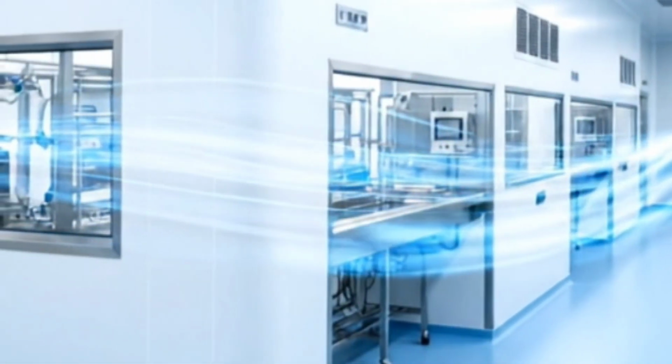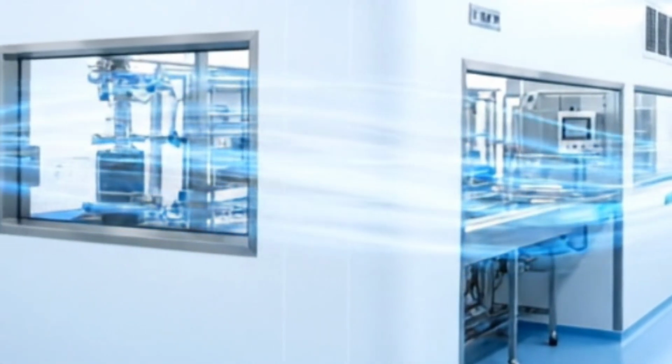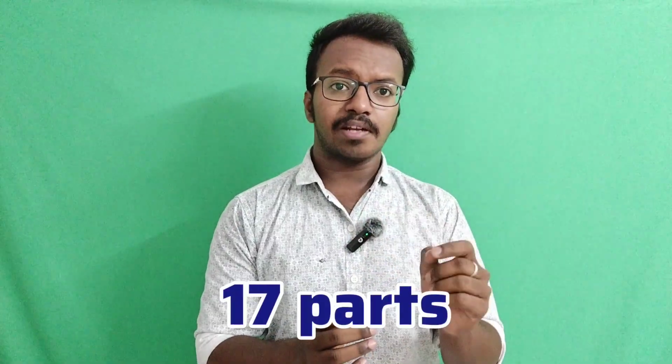ISO 14644 mainly focuses on air cleanliness based on the particle count in the clean room area. As of 2026, ISO 14644 consists of 17 parts. All these parts are required for clean room qualification, but mainly four parts are very important: Part 1, Part 2, Part 3 and Part 4.